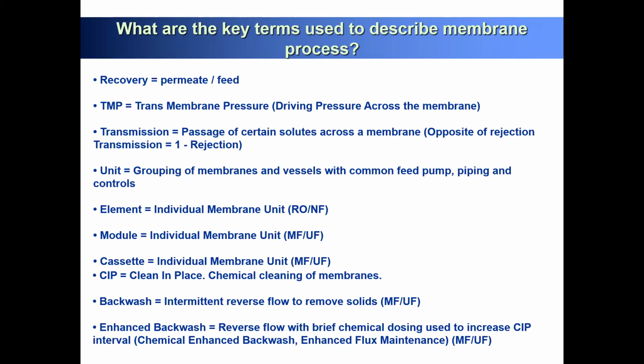So you have fouling, then the pressure has to be higher when you create a consistent flux. So that's exactly why we are monitoring the transmembrane pressure. So we call it TMP. So TMP will represent your overall fouling impact. So we have to also look at the TMP carefully.